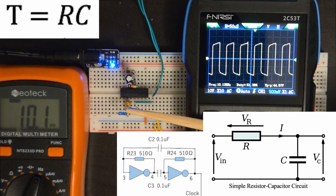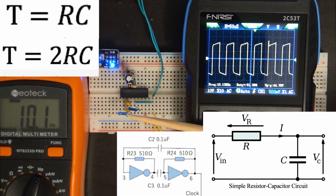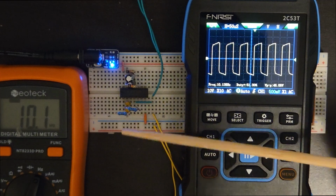The period here would be equal to 2RC, R being our resistance value of 510 ohms, and C being our capacitor value of 0.1 microfarads. That equals about 2 times 51 microseconds, which is 102 microseconds, which is our accepted period. And then using the calculation for frequency, 1 over period, we get a frequency of about 10 kilohertz, which again is within our accepted range.